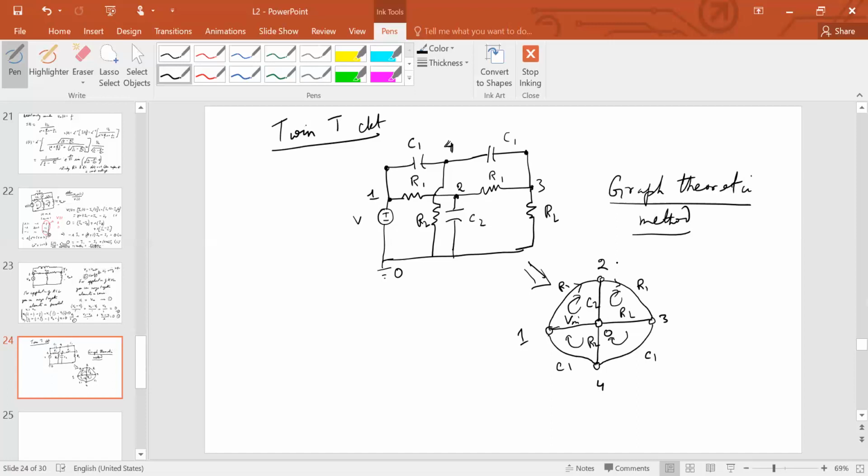So basically, assign voltages to these nodes. So call this V2, V1, V4, V3. So basically V2 minus V1. So the way it is written here, it is very easy to use KCL here. Of course, you can also use KVL. But the point I'm trying to make here is that when circuits look a little more complicated, it often helps to draw out a planar graph such as this, which then makes it easier for you to see the circuit in a new light. And then you can again apply the standard techniques of KCL and KVL that you are so familiar with.